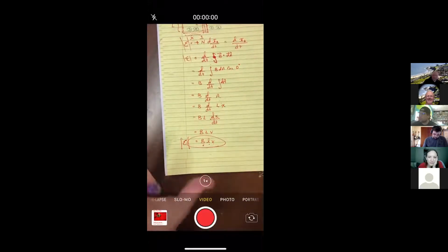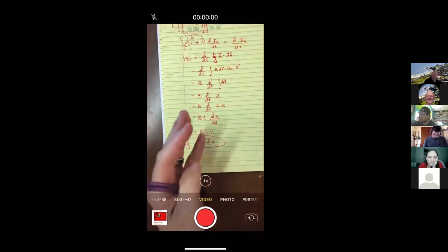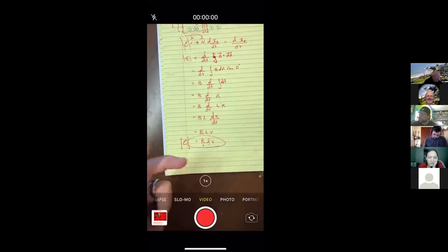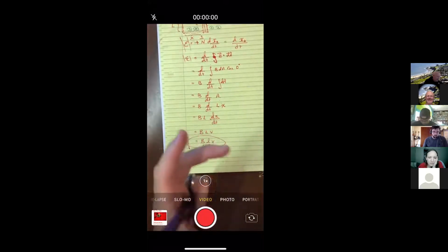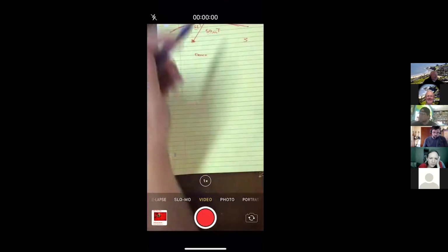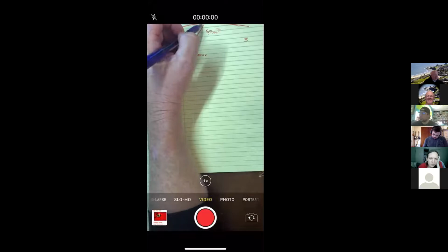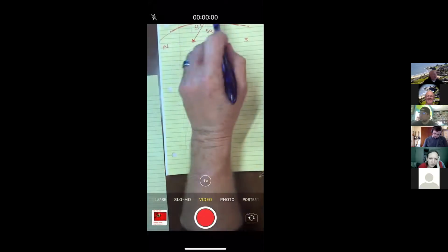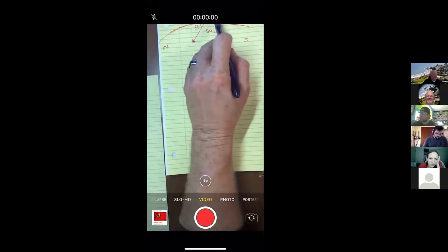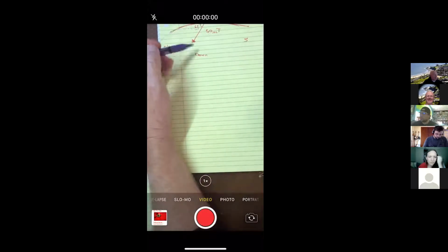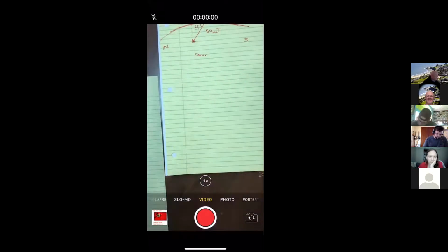So this antenna will produce an EMF if I match those 3 conditions. Those 3 conditions are matched if I have a vertical antenna traveling either east or west, and the only part of the field I care about is the horizontal part pointing north, not the part that's going down.